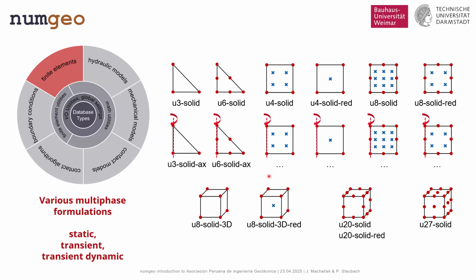Just to give you a quick idea, you can perform plane strain simulations, which are the ones in the top row, so they just give a small excerpt. You have linear triangle elements, quadratic triangle elements, and then you have the rectangle elements, again, linearly or quadratically interpolated, with different integration rules, as you can see, fully integrated, but also with a reduced integration.